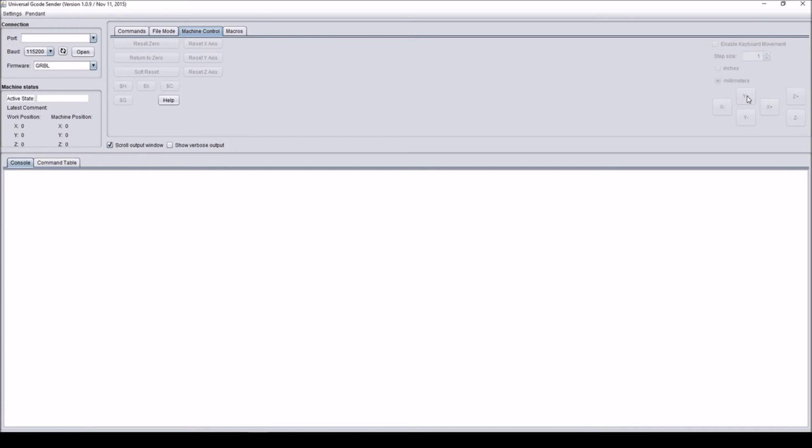To zero a machine, simply move the machine's bit in the Y, X, or Z axis until it makes connection with material. Once it has made connection with material, reset that axis, and now you will be 1 tool radius away from 0 in that axis. Do this for all 3 axes. Now move it to that position, then move the X and Y position 1 tool radius towards the part. You will now be at the correct 0 position.